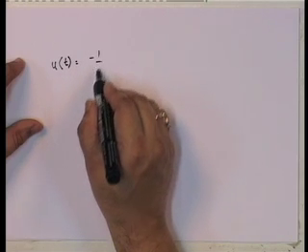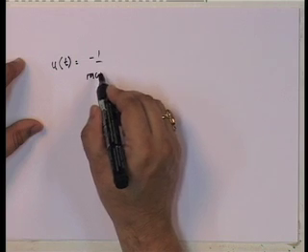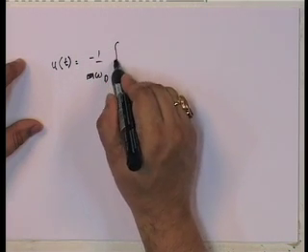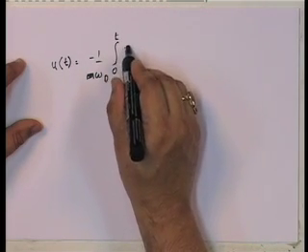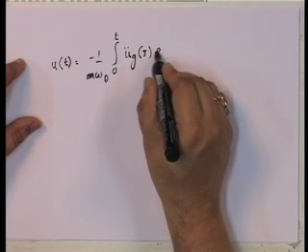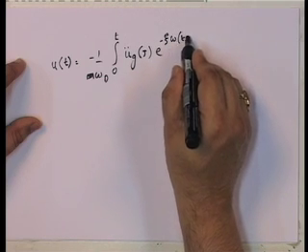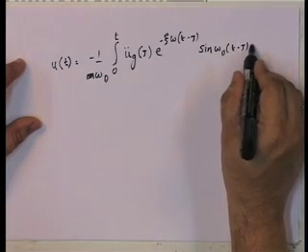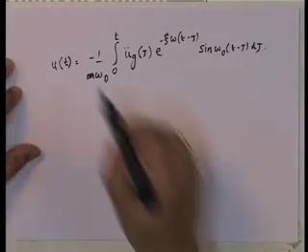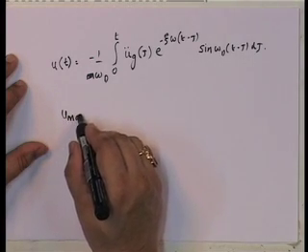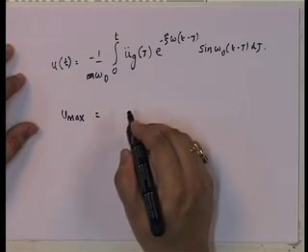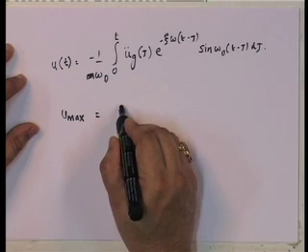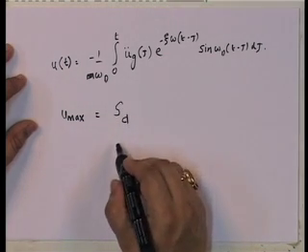Okay. Now the question then comes back, if I go back to the original equation and the original Duhamel integral, the m goes away, it is 1 over omega d, integral 0 to t of u double dot g of tau e to the power of minus xi omega (t minus tau) sine omega d (t minus tau) d tau. So, if you look at this, what does u max depend on? Of course, it's u max. I'll define this as, what does this depend on?